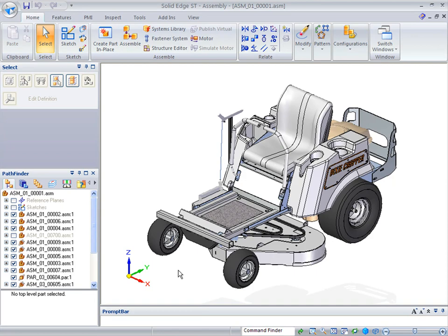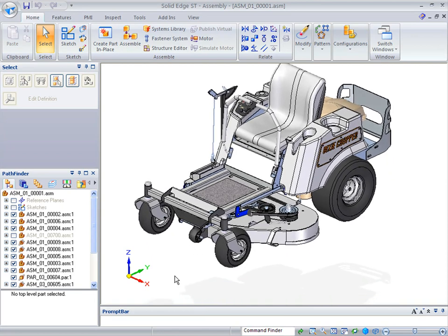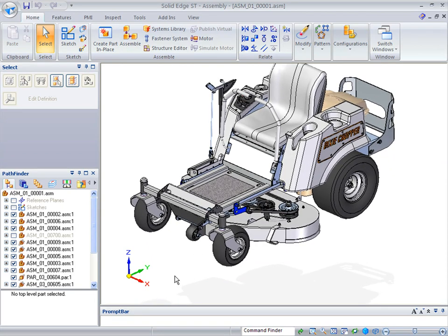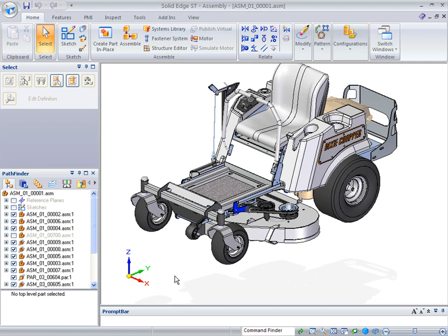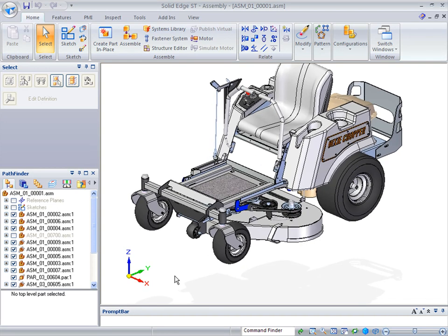The intention of this demo is to show some of the functionality that assembly modeling has brought to the user with ST2. The concept that we want to show is the ability to assemble components against a 2D sketch that contains intelligence. The components will be constrained to the sketch, so we can come back later, make changes to the sketch, and have the assembly model update as we complete the model, check for interferences, and continue with our work.